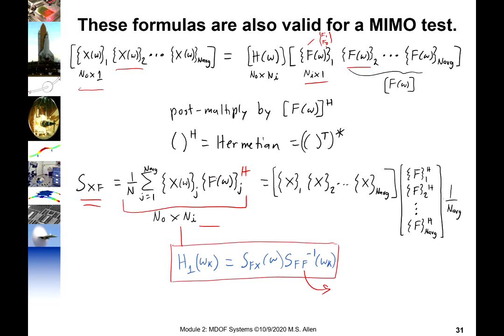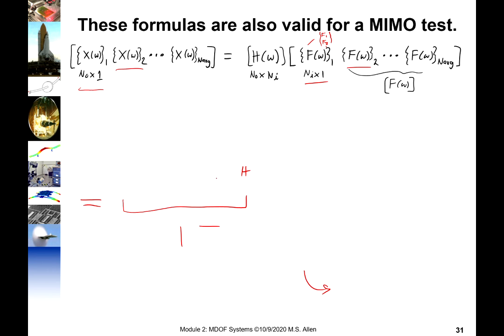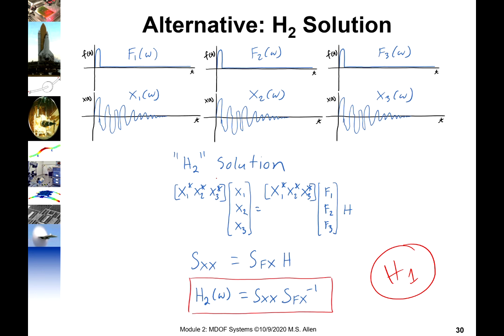In many of them, in fact, to get time histories, you can only get the time history for the last block. So if you did 3 averages, you could get this time history, or you can store and get the FRF or these autospectra. But you have to go through some extra steps, what's called throughput recording or something, if you want to actually record the time histories.